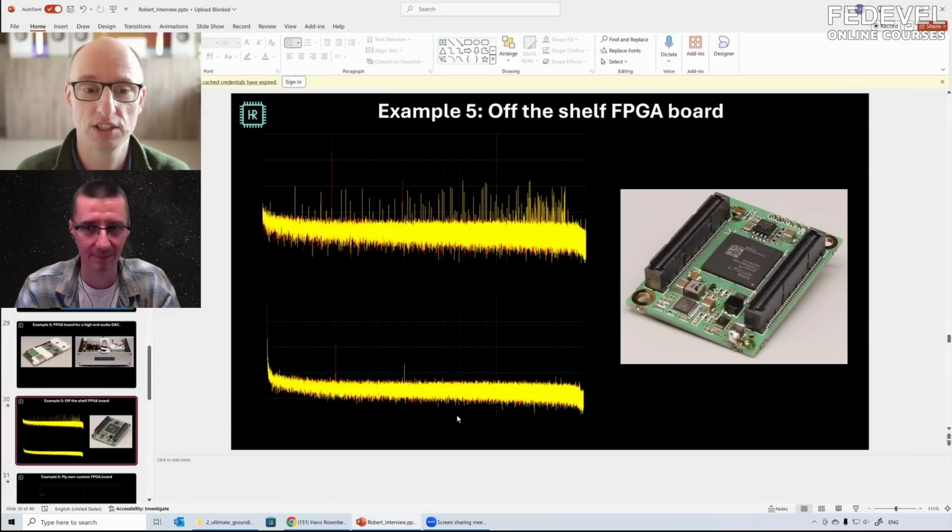You know, if you have 6 or 8 layers and micro vias, making a board like this in the right way is a piece of cake, really. Unless you want to connect every little I/O, then you still have to be careful. But I wanted to stick to 4 layers with standard through-hole vias. And so I finished the layout.